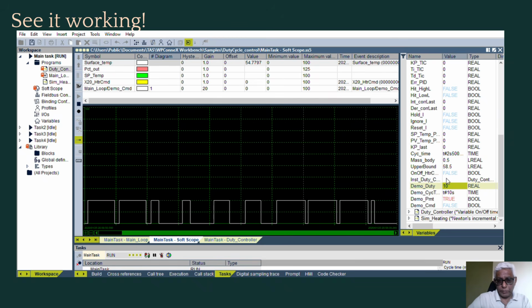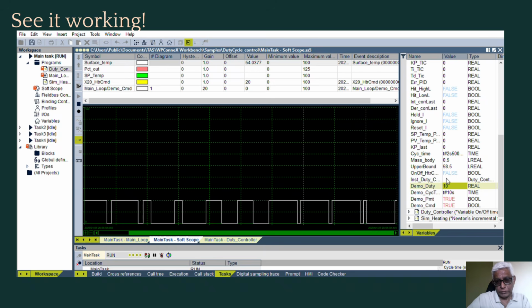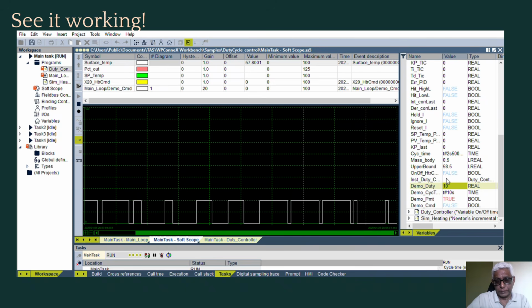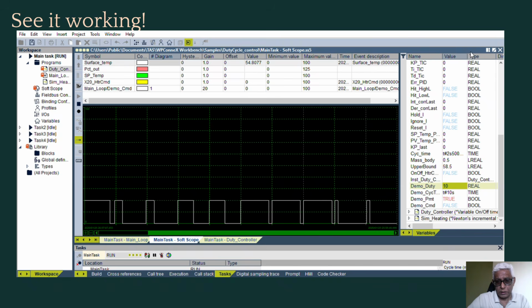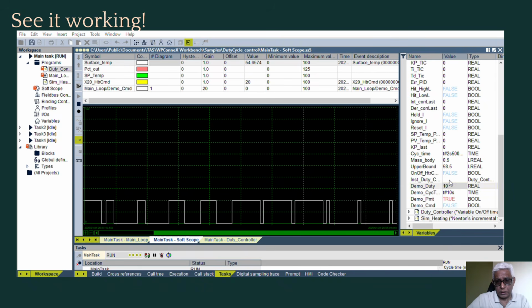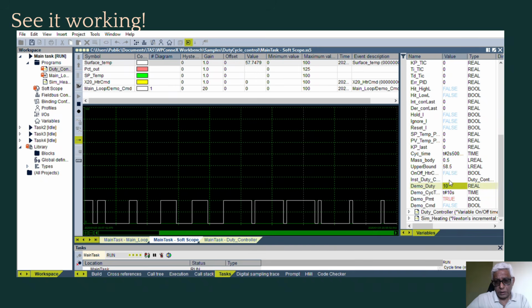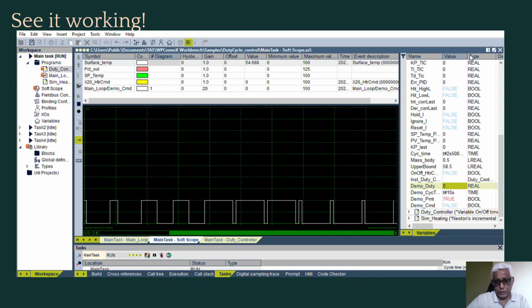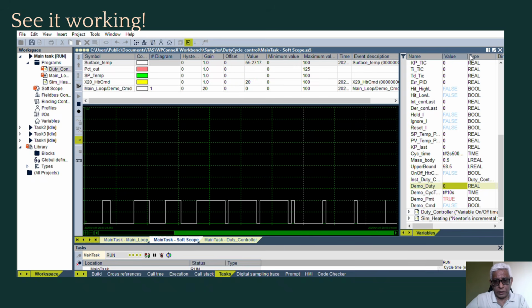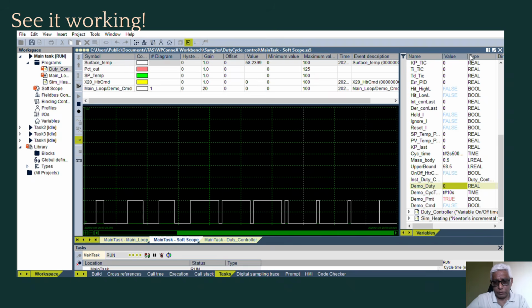Finally, we'll see if it completely switches off at 0% duty. And so it does. 0% duty, you get only the time marker, the output is never on. So we can trust that function block and then attach it to a PID block and see how it behaves, how accurate it is able to control.